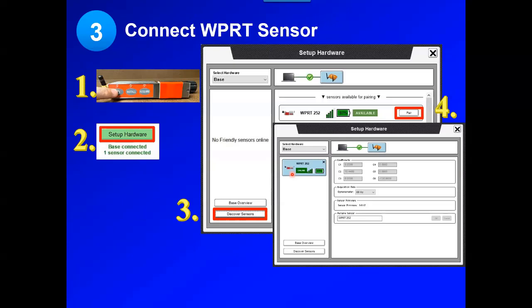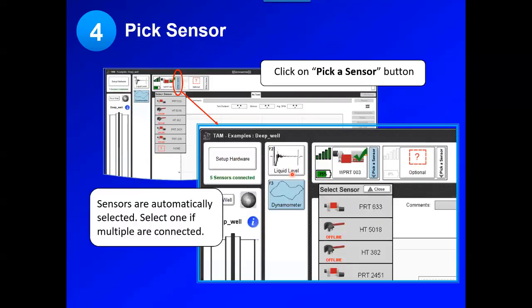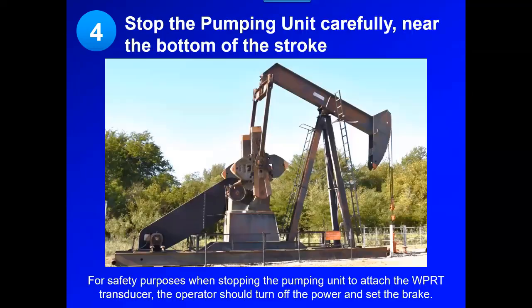Very similar with the wireless PRT as well as the HT that we'll talk about. Now, with the PRT, you don't have to get a zero offset on it that we'll talk about with the HT. Okay. However, with all sensors, you do want to make sure that the sensor is picked up at the top of the toolbar. If the sensor that you're utilizing is not present, you're going to click on Pick a Sensor, go down and select the appropriate sensor that you want to use. Okay. Most of the time it comes over automatically, but if it's not present, go up, pick a sensor, and go to that particular sensor.